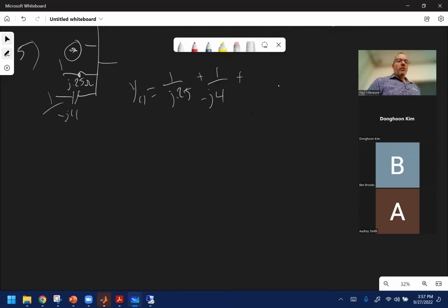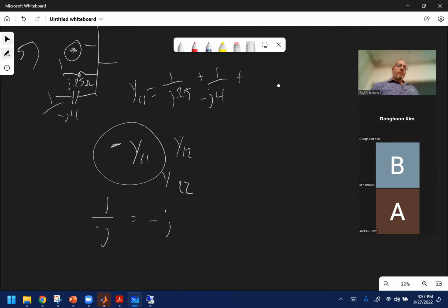Sure. So usually all the diagonals are going to have negative real parts, sorry, and all the off diagonals are going to be positive. That's because most transmission lines look primarily inductive. Some are capacitive, but they're primarily inductive. So if I do 1 over J, that's minus J. If I put it in the self-admittance, it just adds together. But the Y12 is taking the negative of the admittance between bus 1 and bus 2. So that's why it becomes a positive number.